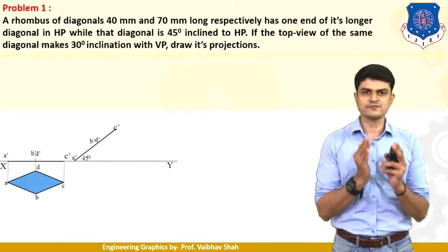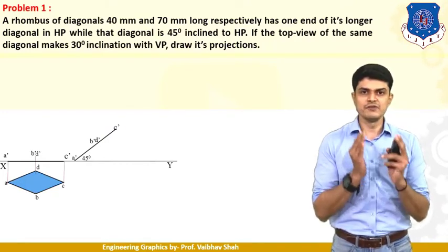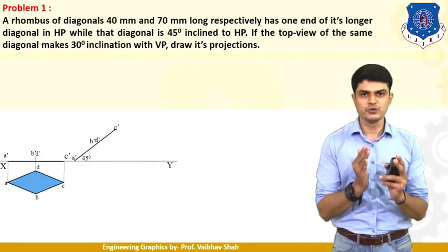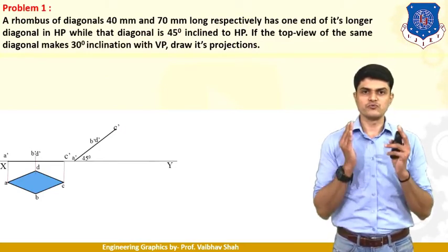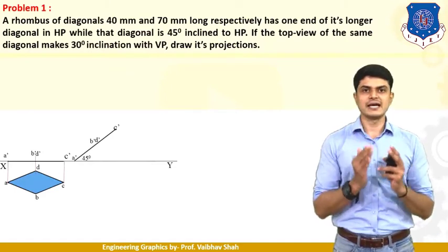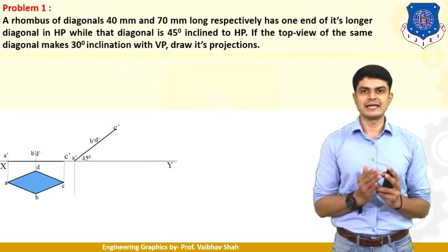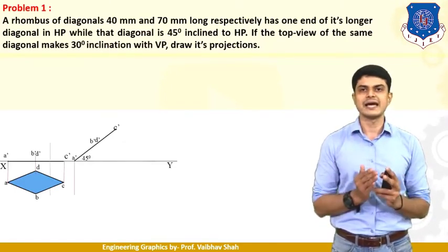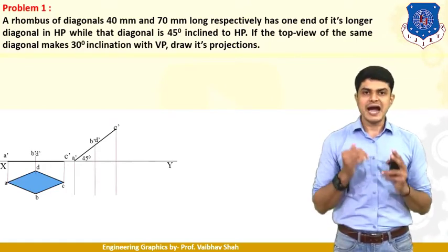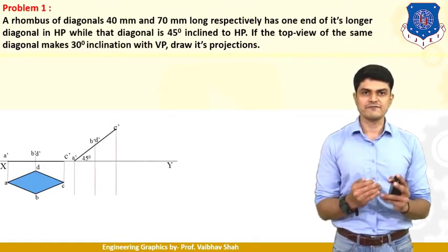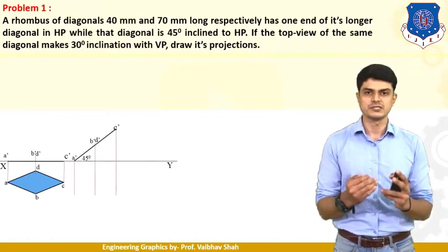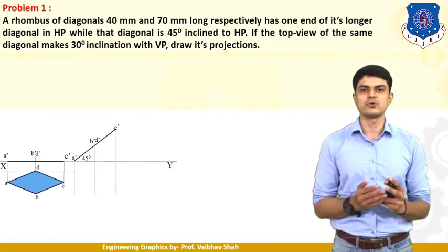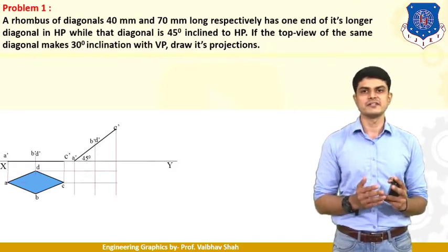Now after having this front view inclined line, we should generate now top view in second stage into HP. So for that what we should do? We should draw the vertical line from each and every point like this. So let us draw vertical line from each and every point. After constructing vertical line, for a reference from your first figure, we should draw a horizontal line from a rhombus. So let us draw a horizontal line from a rhombus in order to get the point of intersection.